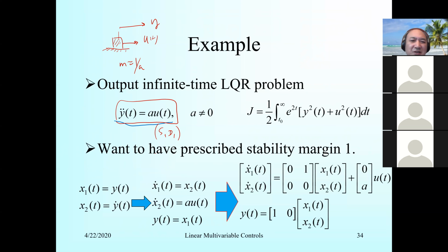So let's do it. The original system in state space format is this: position dot is my velocity. So this is velocity, this is the position. So position dot is my velocity, and velocity dot is A U, okay, A and U. And I assume that the observation is CX. C is only position; position is observed.